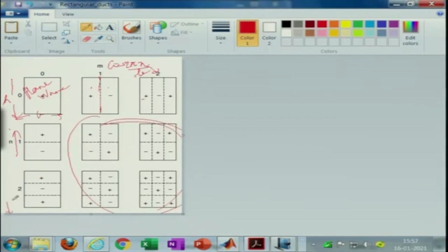So, if you go along this direction, these are modes along the y direction, but there is no variation along the x. Similarly, here you have variation along the x, but no variation along the y. And these modes are all cross modes, where there is simultaneous variation of acoustic pressure along both the x and y directions. This obviously comes out very nicely from applying the boundary conditions as we saw, and they are nothing but plots of the trigonometric functions. So, this is a very classical, very well known solution.